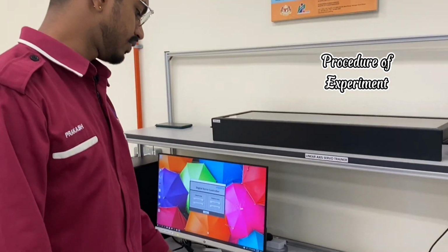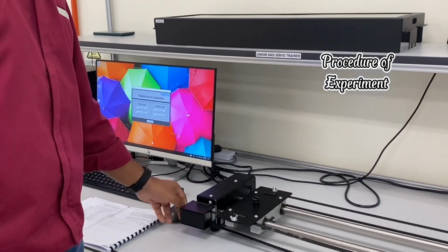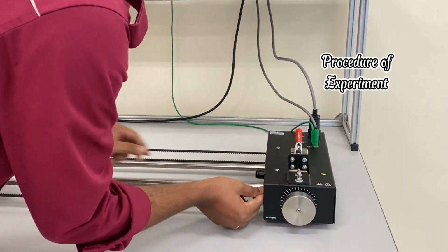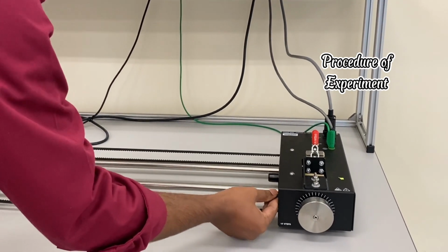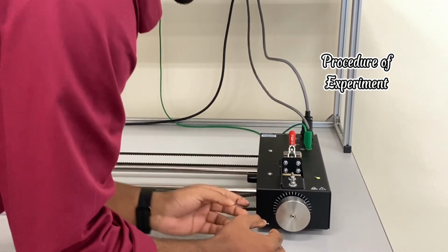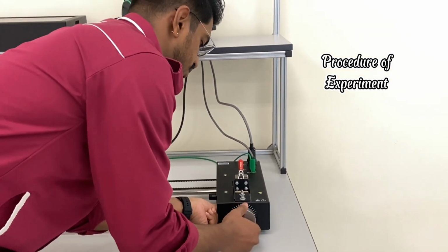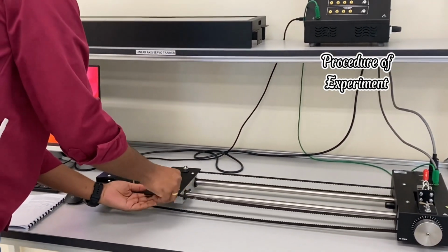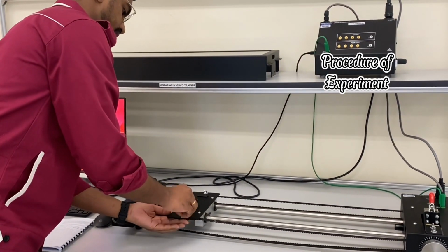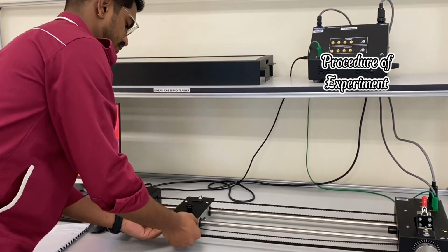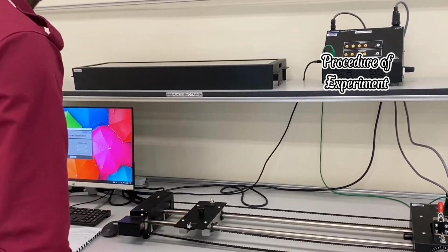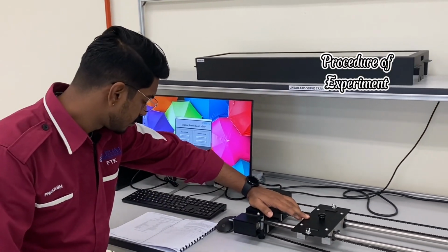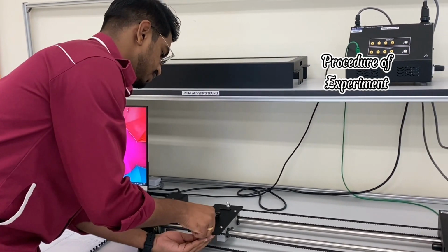This belt tension we have to untie, so we pull it out from the shaft because we don't want it connected with this. Secure the flywheel shaft above the action. So yeah, remove it.